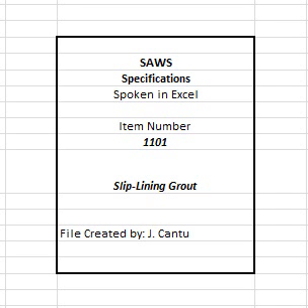C. Sampling. 1. Take 4 test specimens for each 100 cubic yards of grout, or for each 4 hours of placing. 2. Test in accordance with ASTM C495/C495M-12 except A. Specimens shall be 3-inch by 6-inch cylinders covered after casting to prevent damage and loss of moisture. Moist cure specimens for at least the first 7 days. Perform at least one compressive strength test of each set of samples at 28 days.